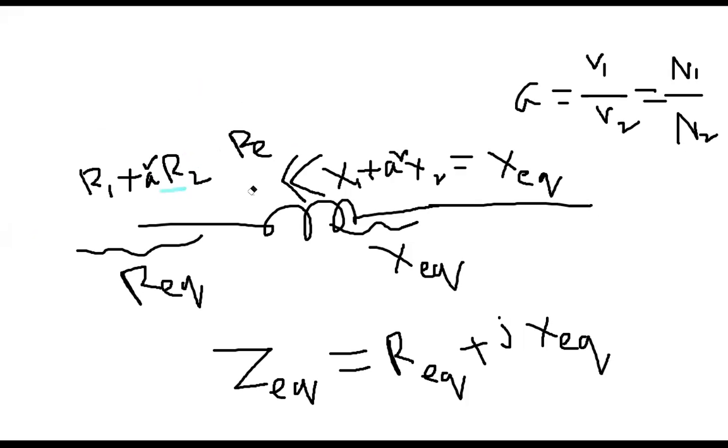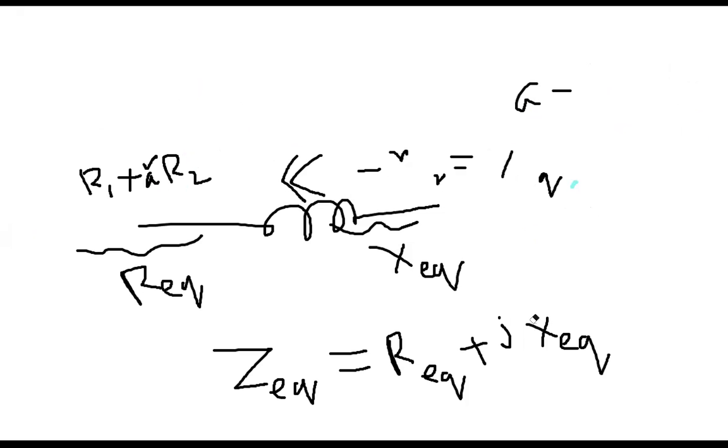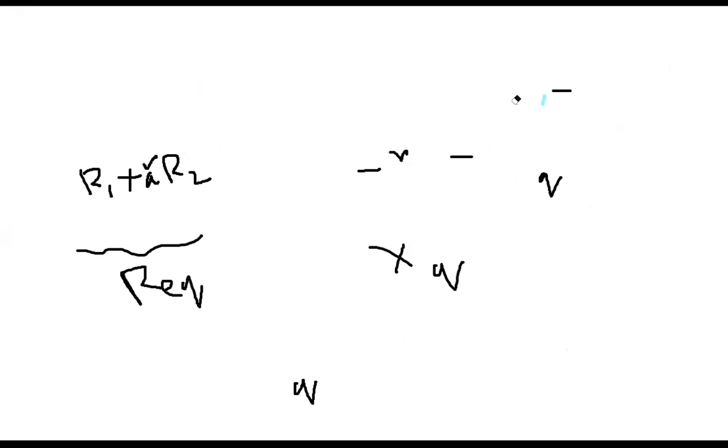Let me clean off all of those things. Okay, first let's go with the short circuit test. First we will be discussing this one, the short circuit test. For the short circuit test, you will be adding an ammeter in the primary.